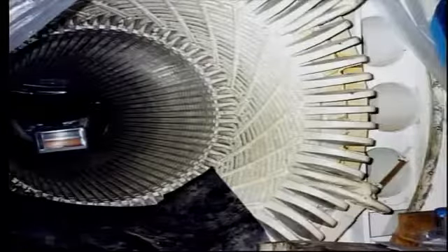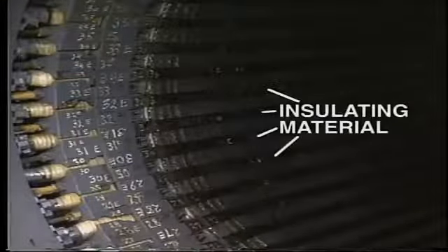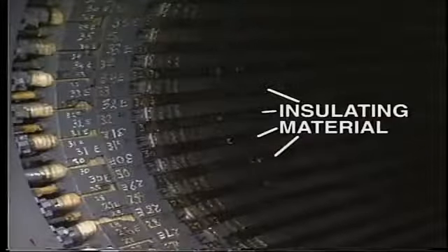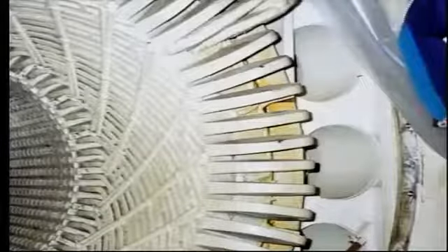Once the stator bars are fitted into the core slots, they are joined at the ends to form continuous coils or windings. These end connections are referred to as end turns. The conductors are securely held in the slots by wedges of insulating material. This is extremely important, as the windings are subject to quite heavy mechanical forces during operation. The windings may try to twist during heavy power surges or electrical faults on the power system.